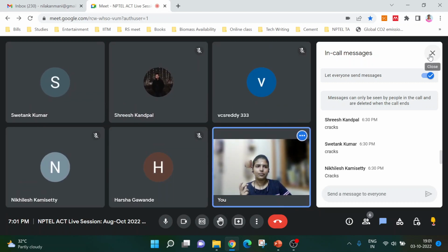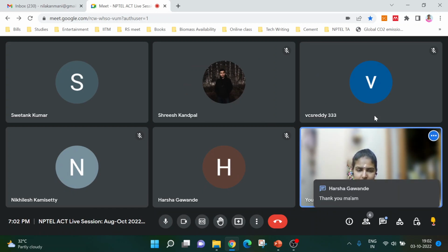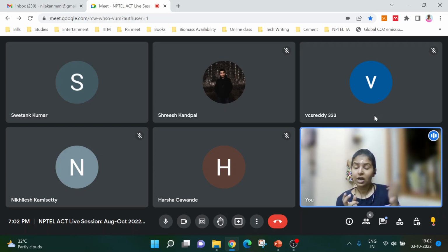So you're speaking about highly reactive pozzolanic material, right? Yes, ma'am. Particularly when it comes to silica fume, it's a highly reactive material and it's very fine as well. When the fine content in the cement concrete increases, the amount of shrinkage will be very high because the amount of reacting material is also high. So the shrinkage also will be very high.